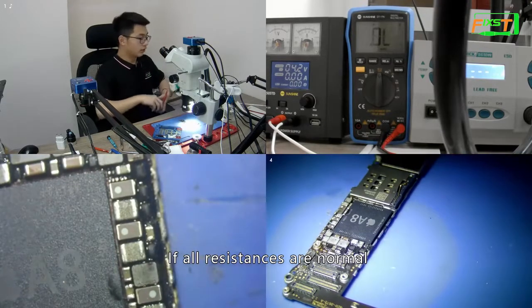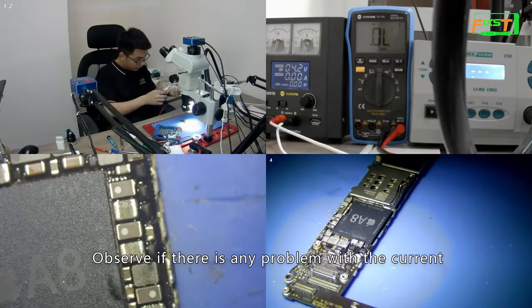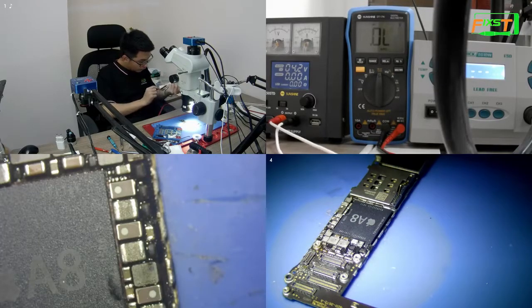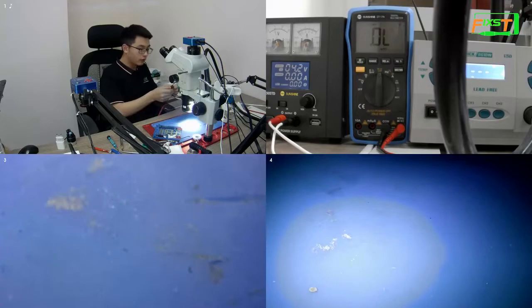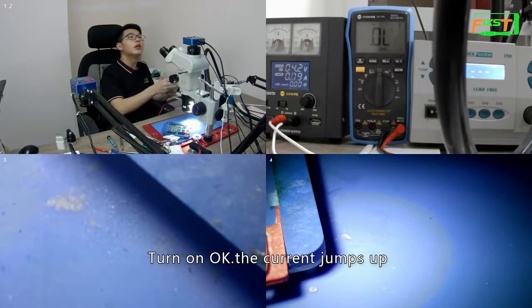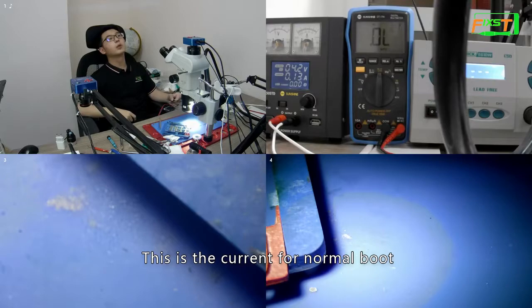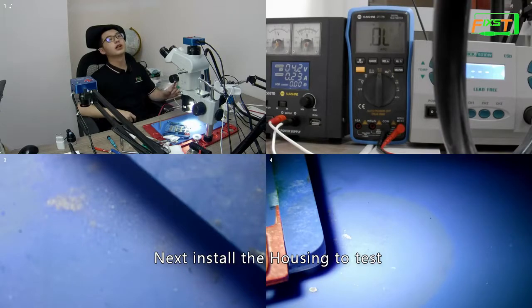If all resistance are normal, we need to test the current. Observe if there is any problem with the current. 0.08, 0.09, start up. Turn on OK. The current jumps up. This is the current for normal boot. Next, install the housing to test.